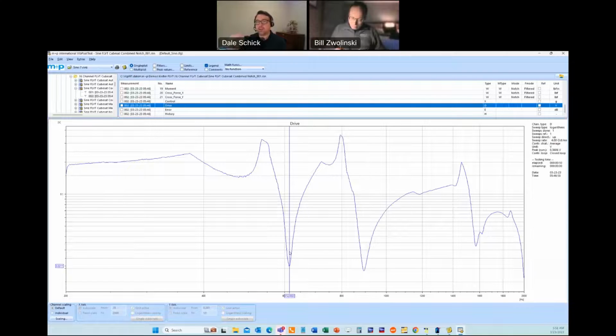So if this were a cross-axis response and the cross-axis response error was higher than the in-axis response, you would suddenly switch over to the cross-axis response. And if you can't cut out any more drive in order to reduce that input, you're going to have a test abort, or you're essentially going to have an uncontrolled system. So this is what I would look at.